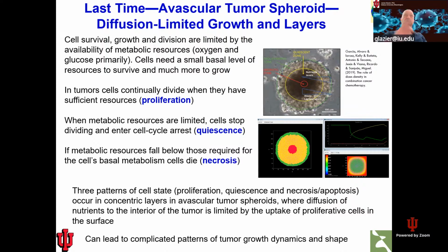In the particular simulation we're doing here, if the oxygen uptake changes when you change the cell type, and you specified the uptake rule not in the Python, but in the XML, when you change the cell type in the Python, it may not update those parameters correctly. That's the issue. Only for frozen cells.